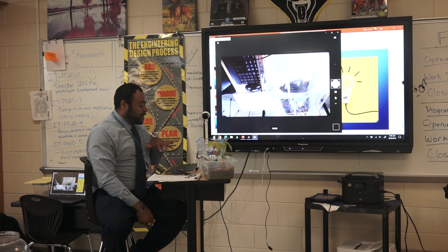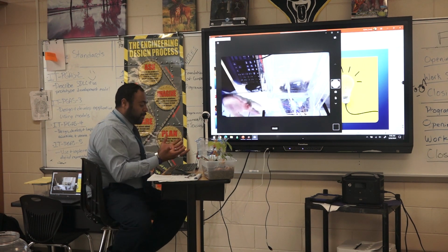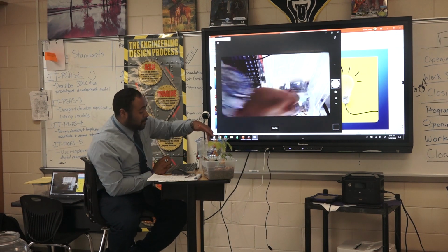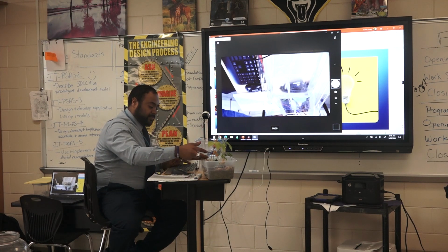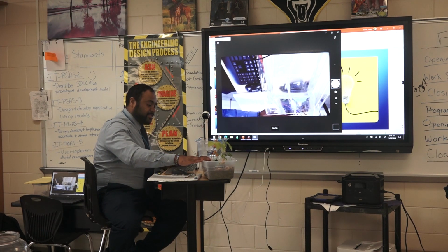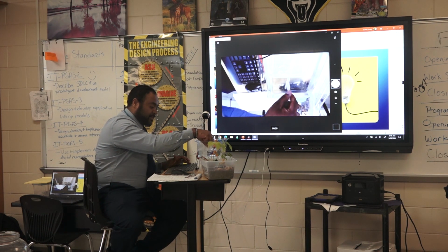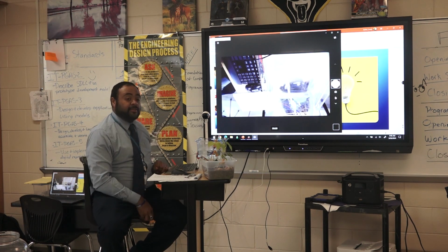When you all develop your iteration of the plant watering system, you need to address that problem. You could poke a hole in the hose, so that when the system detects that the soil is moist enough, the water will go back down because of that small hole in the hose. Or you could go about repositioning the hose.